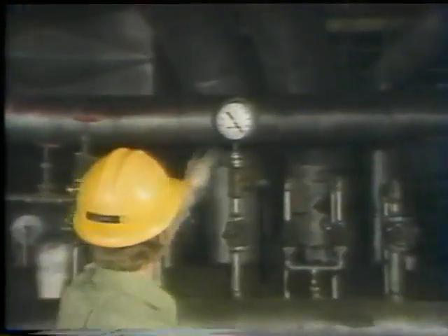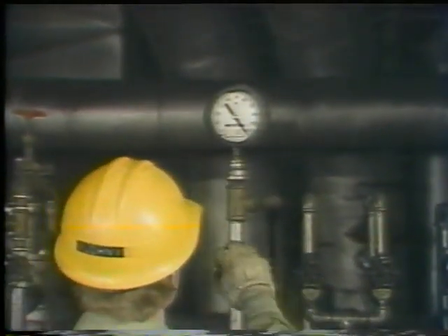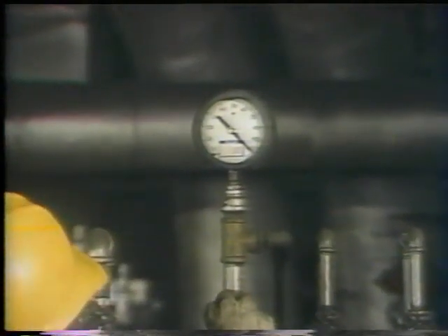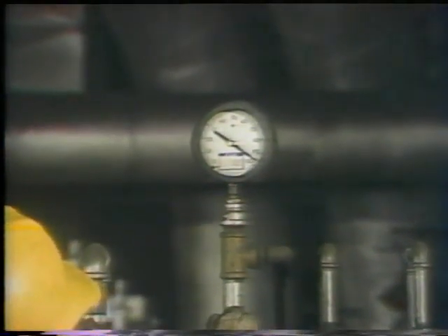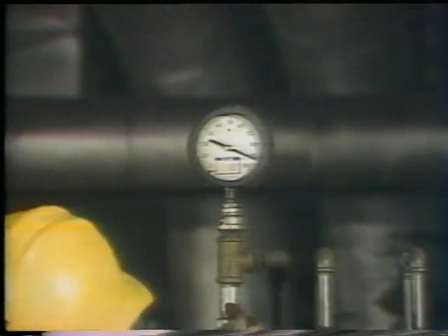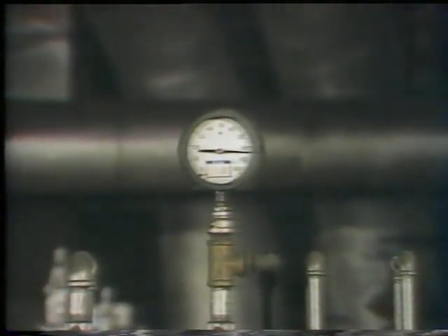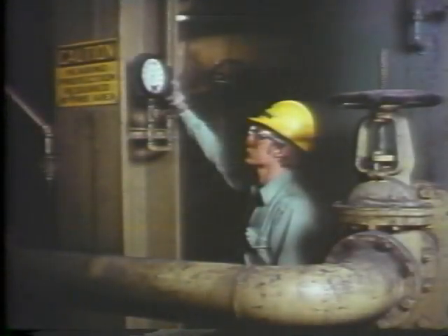If during your routine checks of the instruments in the plant, you find a gauge that is continually showing maximum pressure or is off the scale entirely, your first action should be to isolate the gauge from the system. This is usually done by closing a valve on the supply line. Once this is done, you should inspect the system and make sure that it is operating normally. This may involve checking another gauge upstream or downstream of the one that is off scale.